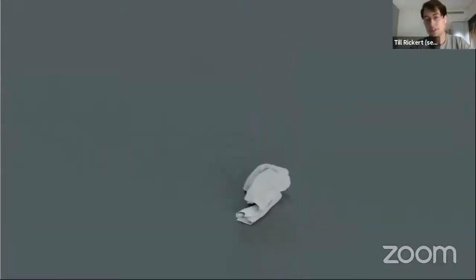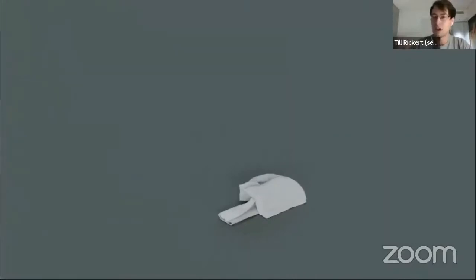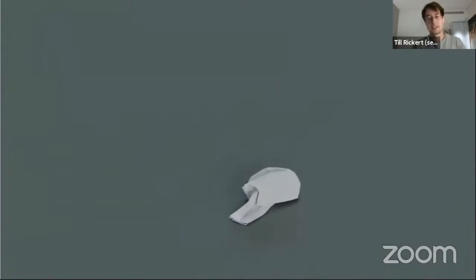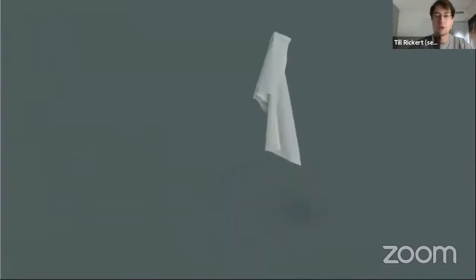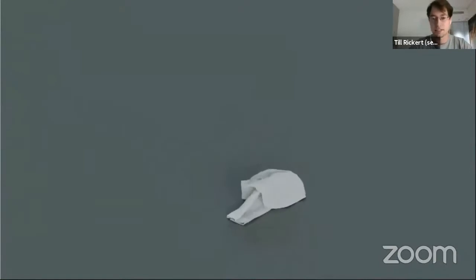Now that you can imagine a little bit better what I've been speaking about with these simulations, I brought a video to you. So what you see here is the simulation of a towel, which is falling down from a specific height onto a flat surface. And this is a video we created only for showing purposes. In our computer vision pipeline, we would only then use, let's say, the last state of the towel, which you can see here, create a synthetic image out of it, have it labeled automatically, and train our computer vision with tens of thousands of those images.